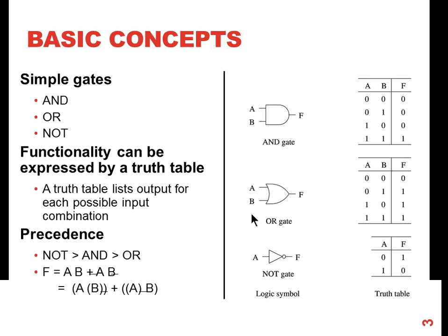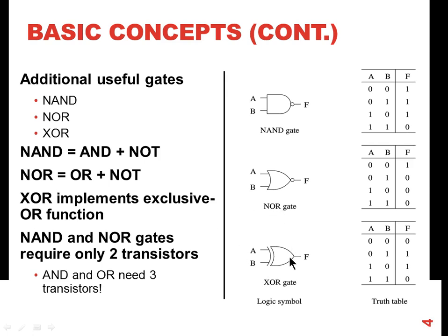But gates and a few other circuits are our fundamental blocks of digital design. And then we'll see how to use Verilog to design various circuits. These are some very basic gates that I will not go through one by one: AND gate, OR gate, NAND gate, inverter, NOR, XOR gate. On the right hand side, you'll see the truth table for these two input gates. For example, for the XOR gate, if both inputs are different, output is 1. If both inputs are same, output is 0.